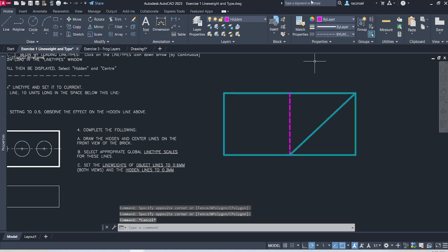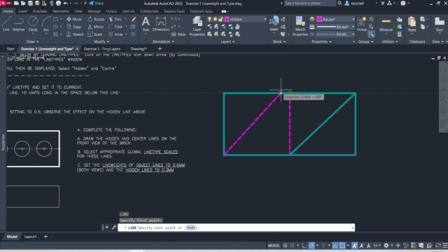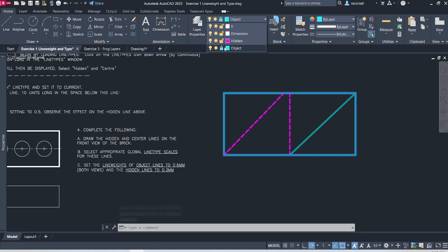So I can still snap to it. If I'm drawing on a different layer, I can go, hey, yeah, I'm still snapping to my objects like I did before. That's no problem. But I can't modify this layer. Protects me from messing up things that I think are perfect.